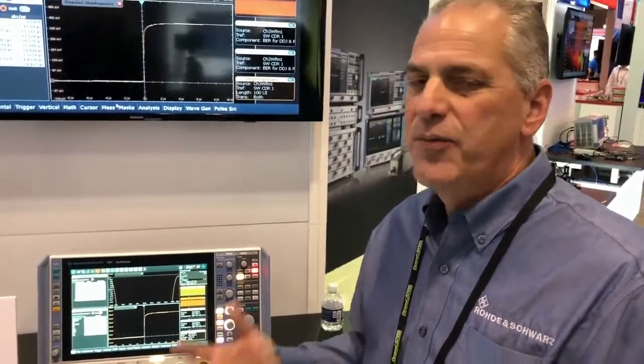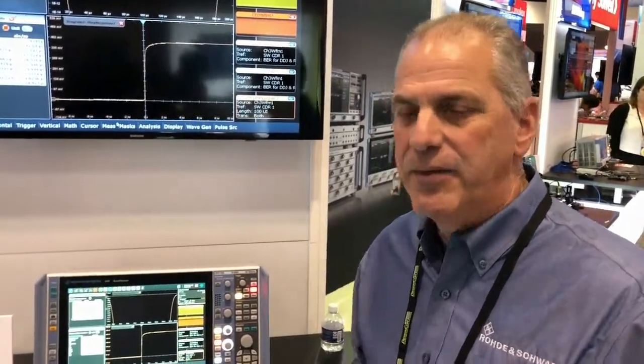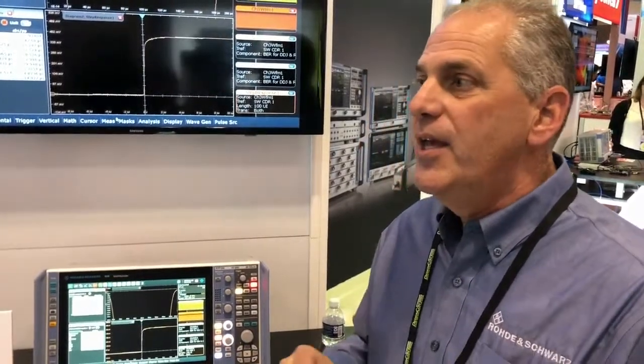One is what I like to refer to as waveform distortion. As the waveform passes down a non-ideal channel, cable, interconnect, or a backplane, or even a trace on a PC board, it's going to distort the waveform. And that distortion results in errors in the edge positioning, and they're dependent upon the bit pattern. Depending upon the bits that went before it, it's going to excite that channel differently and cause different delays through it. That's the one source of jitter that is most common, most problematic, and in a lot of ways easiest to fix, because that just means changing the channel.